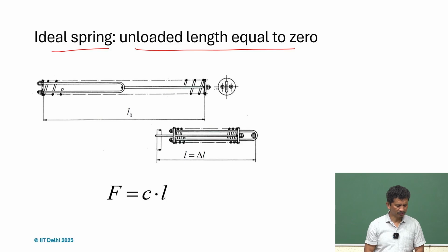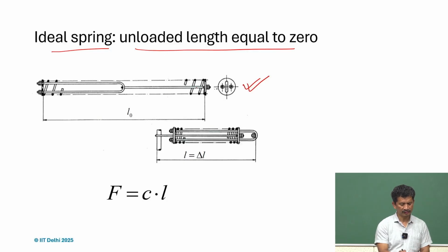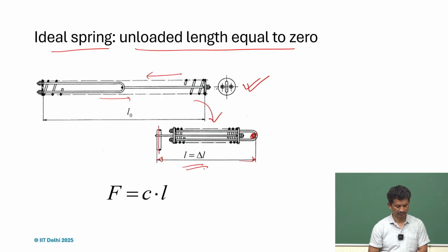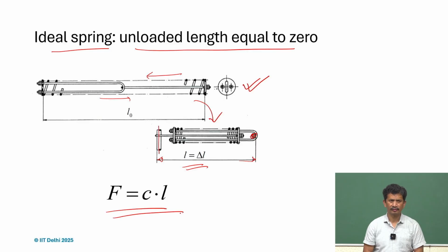The other possibility is, if we see here, here's the spring, and it's a star like this, and this can be pressed, and then we can connect the parts like this and like this here. So this L is delta L all the time of the individual springs, and here F is the stiffness times L. So this is one of the ways.